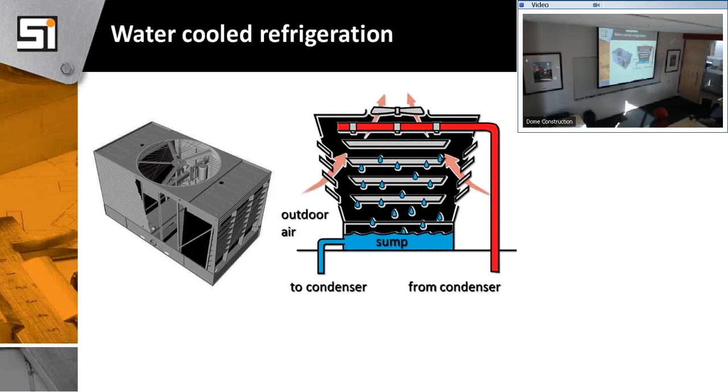Okay, cooling tower. Again, these are associated with chillers. You're seeing a bunch of water and fans going through your big fan here, drains. So now I know typically, there are exceptions, but I probably have a chiller somewhere. So again, this is rejecting heat for the chiller.